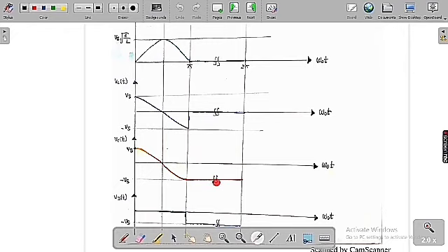So the capacitor voltage will stay the same, equal to minus Vs. Now I am going to write the KVL in this loop when the diode is off: plus Vc of t minus Vd of t minus VL of t is equal to 0. At omega t greater than pi, VL of t is equal to 0. Therefore, Vc of t is equal to Vd of t. Whatever the Vc is, Vd should be equal to it.